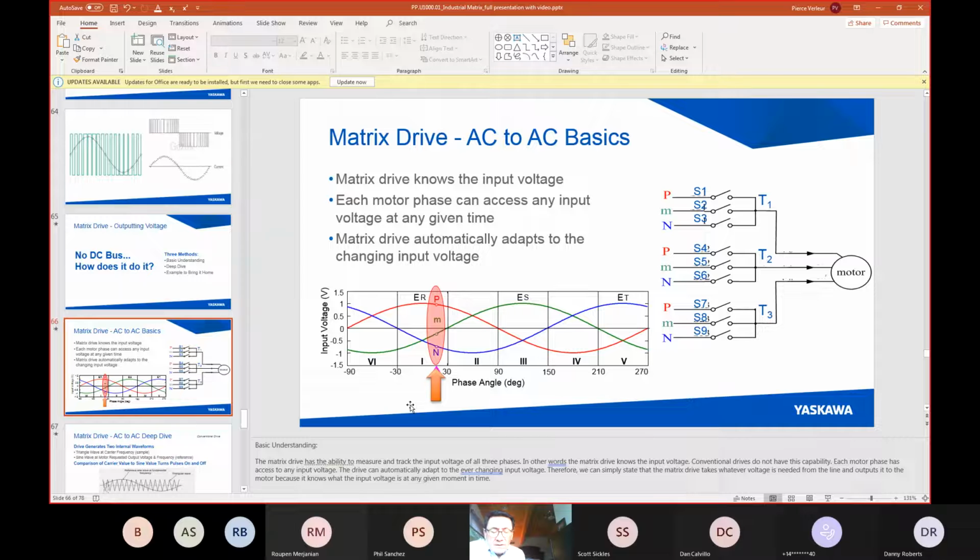So in the case, for example, where you would have a winder, let's just call it a converting line, where you have an unwinder and a winder. The unwinder is going to have material pulled off of it by the winder, and it's going to resist that pulling in order to create a certain tension on the web of material that is necessary for whatever we're doing to that material in between the unwind and the wind.